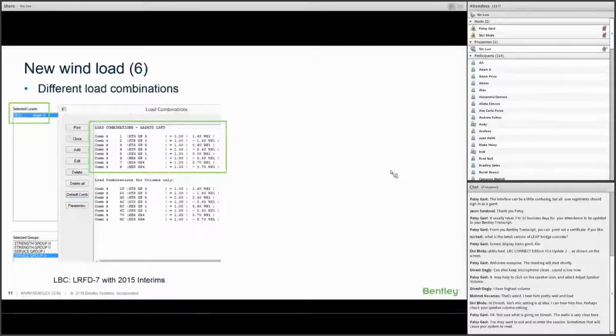Let's take a look at a typical example of an auto-generated load combination involving wind load. On the left side, it shows the results per the old code. For one wind attacking angle, here it is 0, the old code generates just one wind load case, here it is WS1. And this one wind load case subsequently is used to generate all limit states involving wind load, as you can see here.